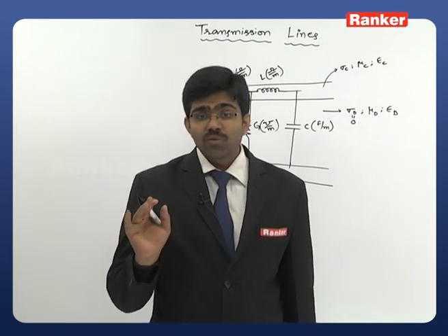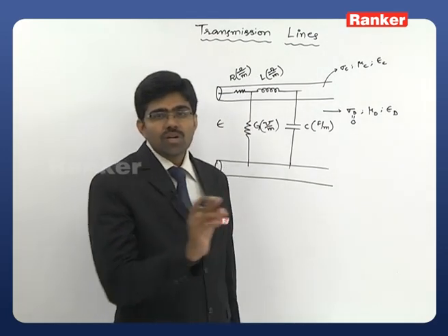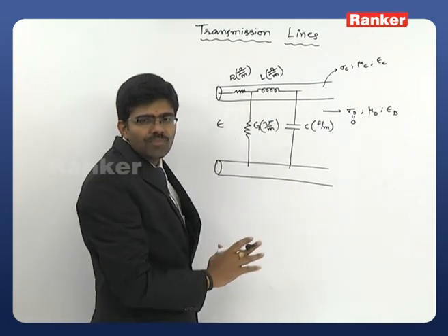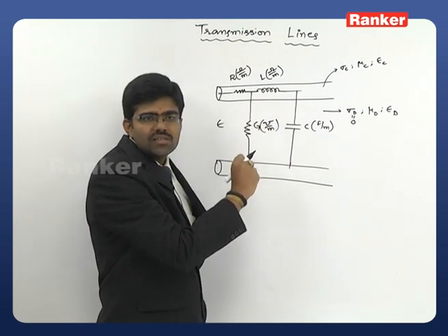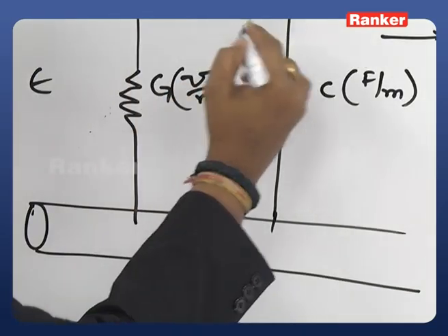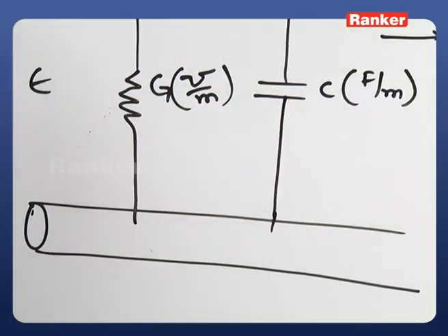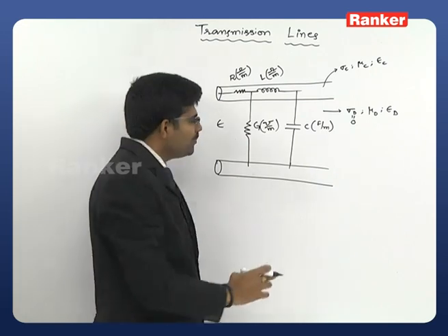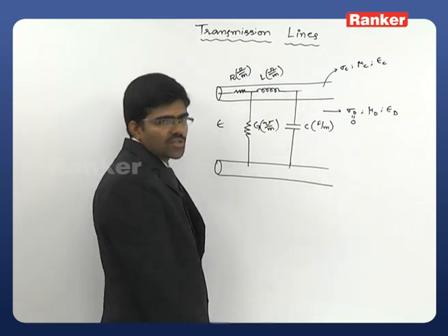So, clearly remember, whenever we are trying to draw the equivalent circuit of our transmission line, just ignore the conductors, dielectrics, etc. Just take these primary constants and arrange them as per your requirement. You can arrange them in a pi order or L order or T shape. For the analysis purpose, you can take the required arrangement for a differential length of the transmission line.